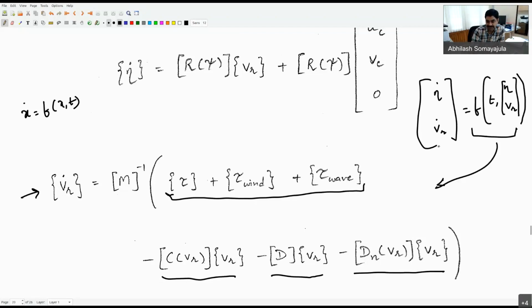Okay, so in essence, this state space formulation is very useful for us, either to simulate the system or to later on discuss about control. Okay? If I ever wanted to do control on the system, to do a state feedback control or a full state feedback or even a measurement based control, this sort of a form in which I'm expressing it in a state space form will be very useful.